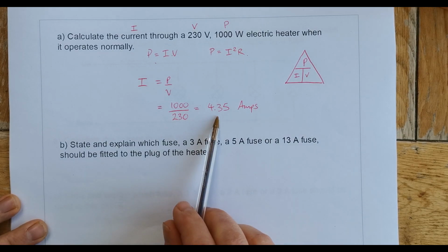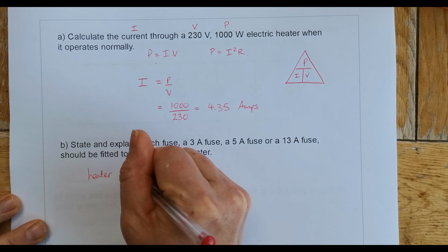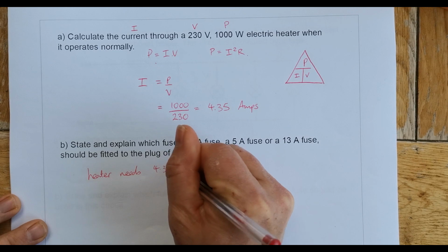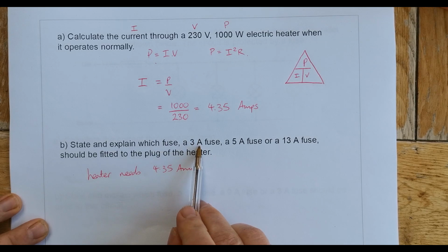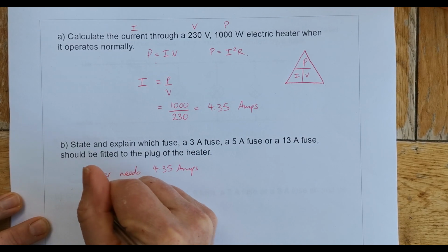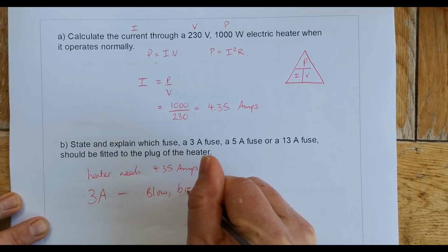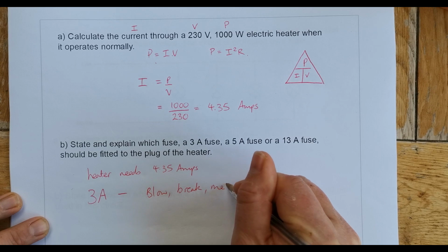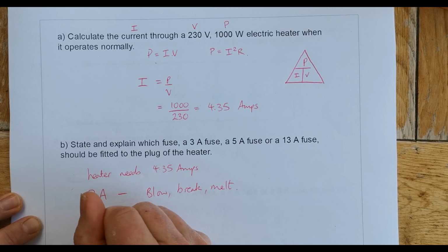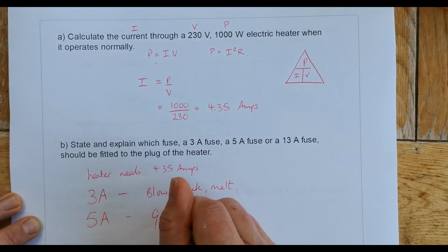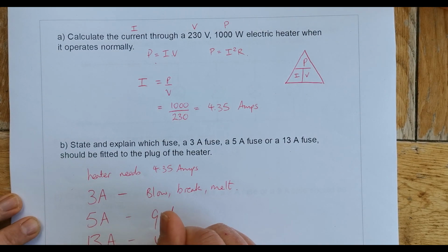Well, this heater needs 4.35 amps to work. So if I put a 3 amp fuse in, a 3 amp fuse would blow, break, melt, because the 3 amp fuses aren't designed for that. A 5 amp fuse would be good, because that should take it. A 13 amp fuse, well, that would work,